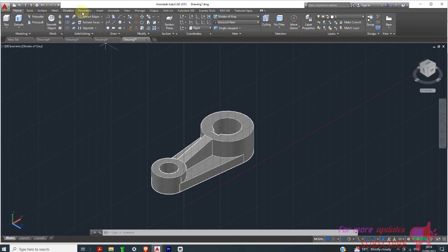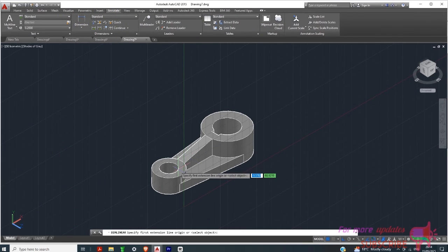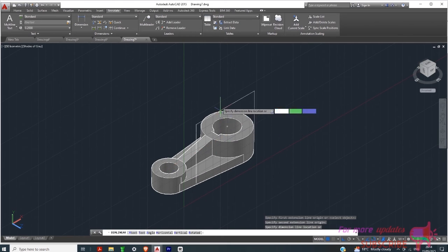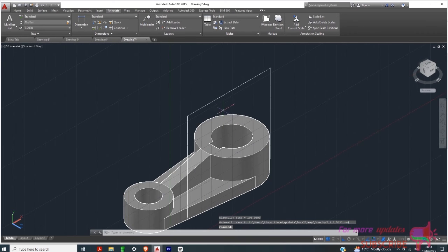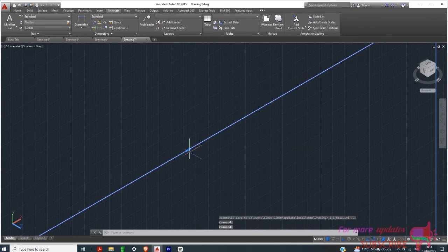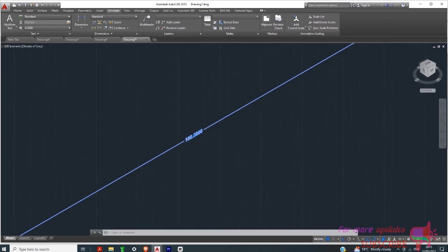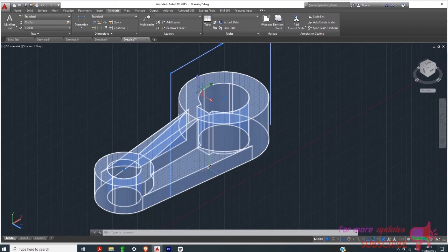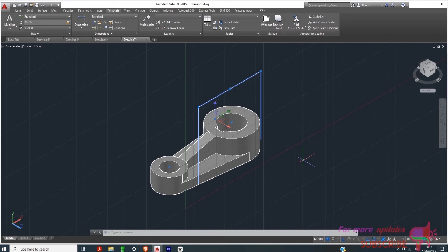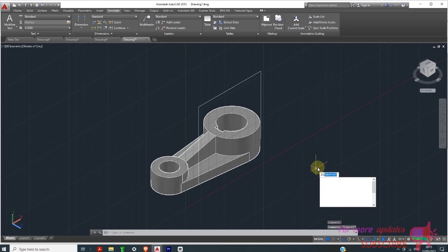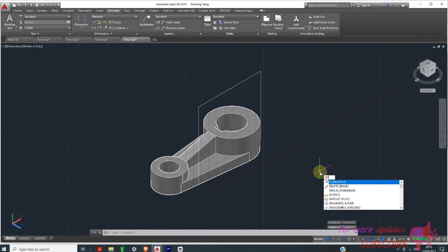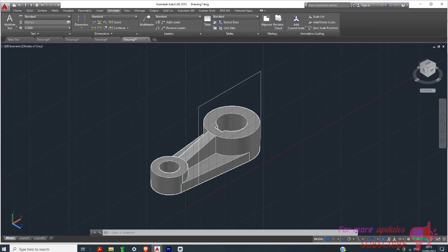Now again, activate annotate, snapping at that center, again at that center, then it's 100, but we need also to change something, and that is type DWG units, and type dim style, and select dim style, that is dimension style.